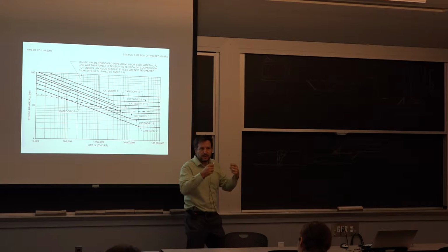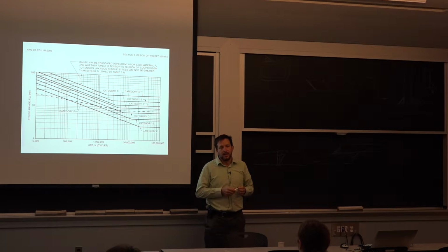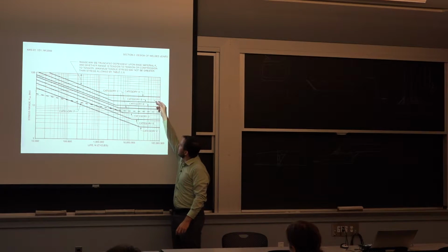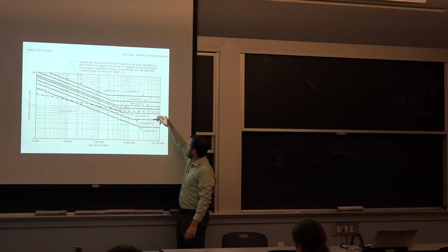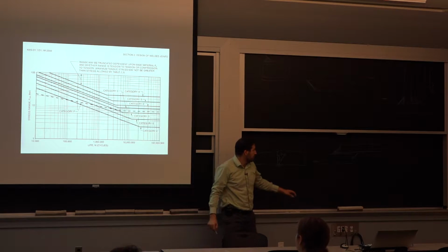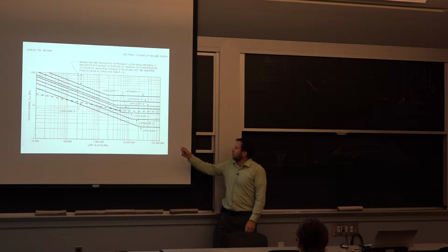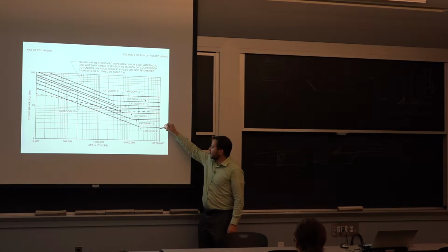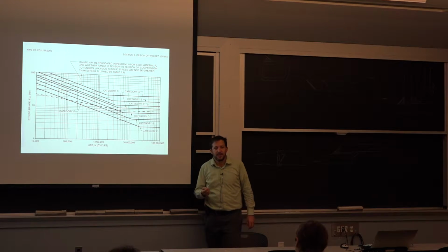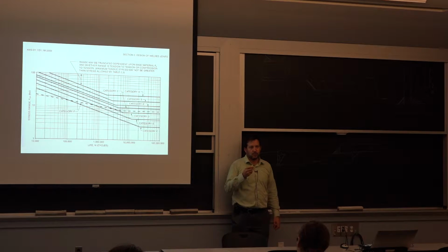Even if it's a cyclic stress, it's going to be fine. Now, as you start going into different categories of welding, all the way to the one I mentioned here, where everything is loaded perpendicular to the weld, your 20, 25 KSI becomes 2.5. So that is a factor of 10.